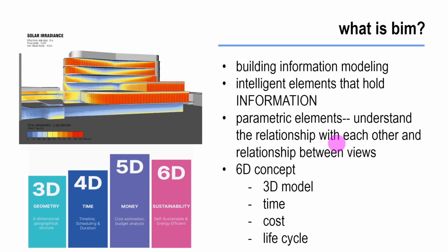and therefore it will only let you put that door within a wall or something like that. And the best part is that BIM is understanding a lot of those standards related to how sets of documents come together. So when I create my floor plan and I put in all of the different parameters related to my walls, so I put in my length and I put in my height, what's also going to happen is that it's going to create my elevations for me as I'm going through. And any change I make in the floor plan, if that change appears in the elevation, it'll update in there too, which is really wonderful and nice. And we'll start to see that with Revit.